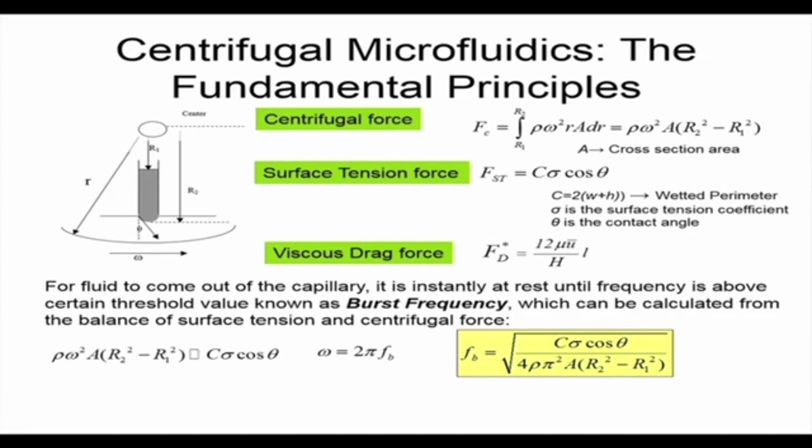Out of that, drag force does not come into the picture for the burst frequency calculation. The reason is pretty clear, because at the burst frequency fluid just starts flowing and there is no viscous force prior to that. So burst frequency is calculated from the balance of centrifugal force and surface tension force.